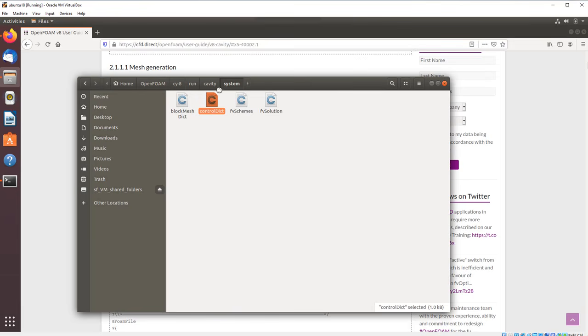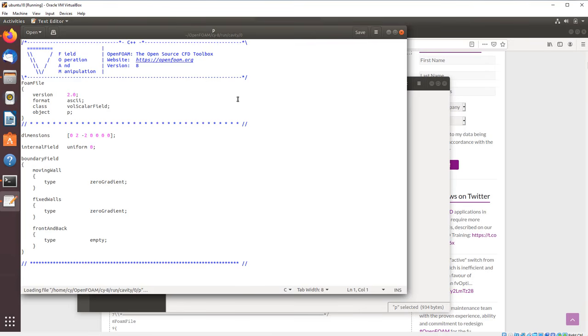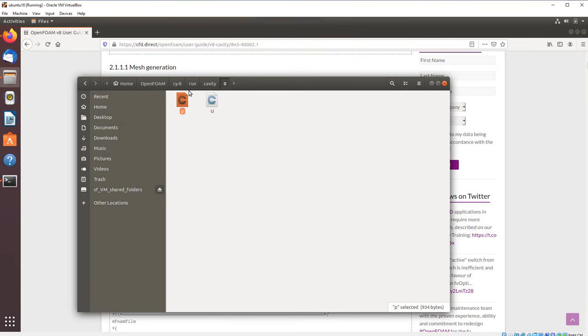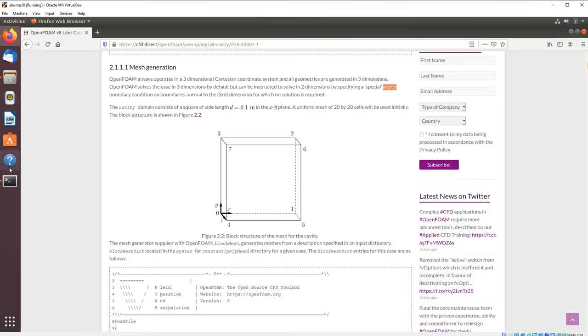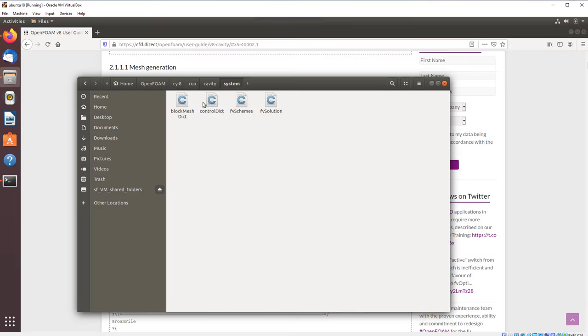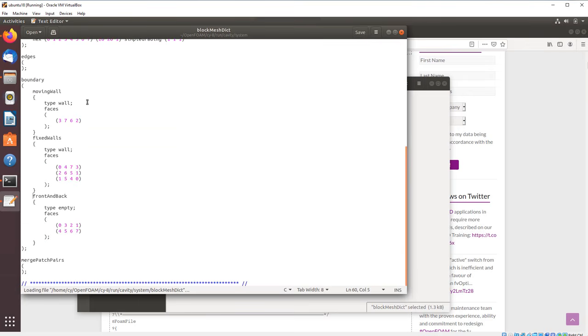So it's probably in the constant. No. Yeah. So when you define the boundary fields to be solved, you give a name to the boundary condition, and you have to maintain the same name here and for the one I mentioned in the blockMeshDict, sorry.